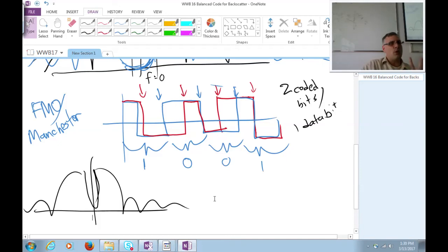And we're limited in what we can do because we have something like a backscatter network where we're just load modulating, switching between two binary different loads. So all we have are square waves, sharp transitions. How do you make something smooth and do all of your signal processing tricks and pulse shaping tricks when you just have sharp transitions? It's kind of counterintuitive that you can do anything like that.